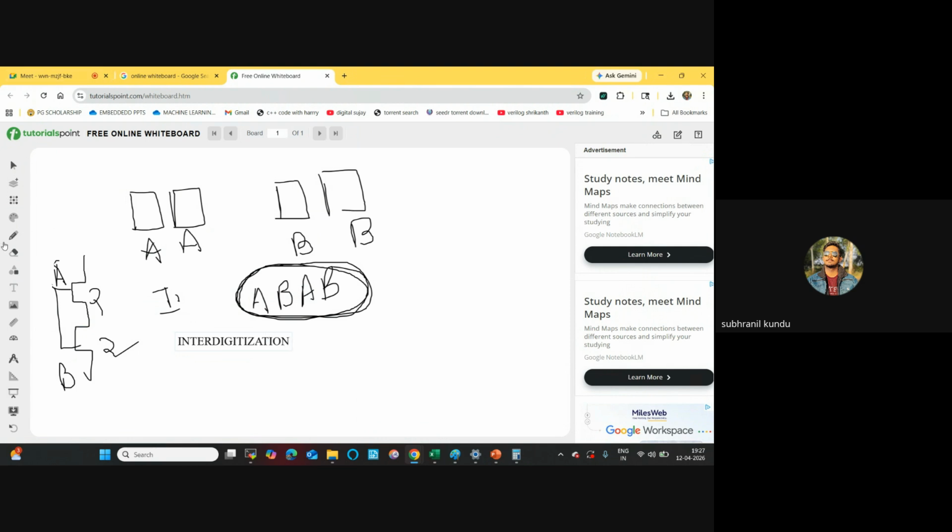And there will be another matching, AB and BA. If I place it, see, AB and BA, or BA, AB. So if you can see these two, each device has a common centroid. That is this. These two devices have a common centroid.